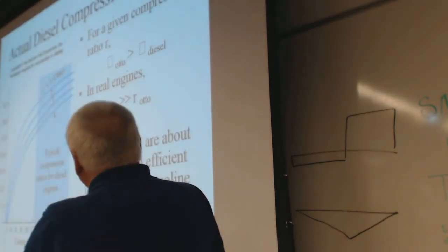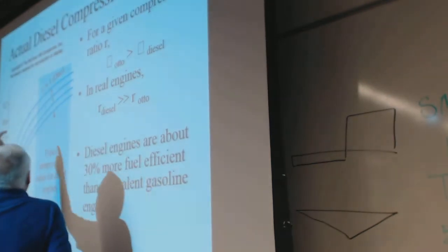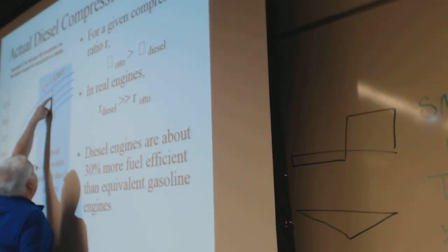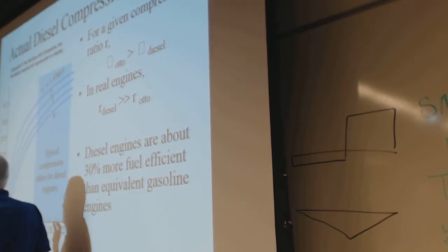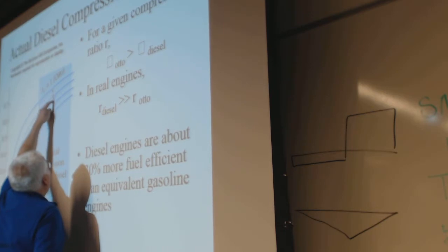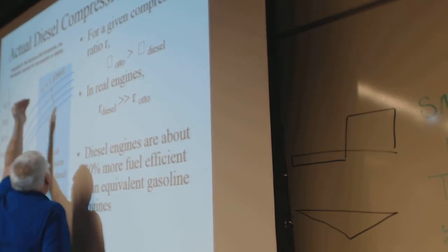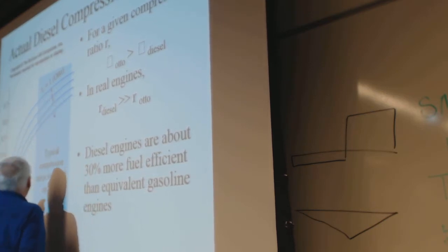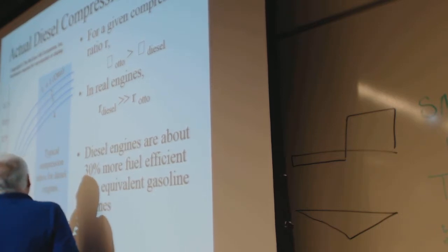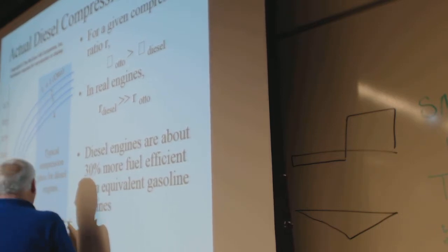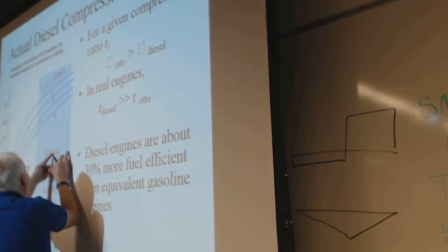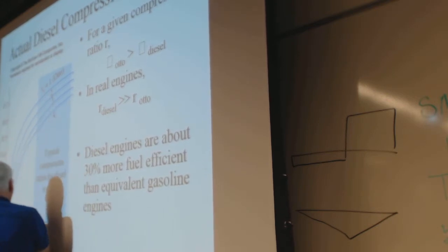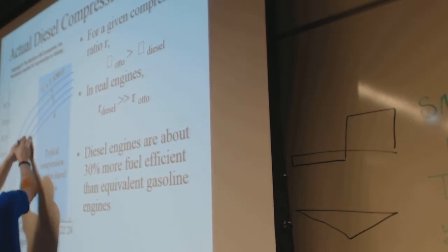As you put more fuel into it, the volume doubles before the fuel goes out. The volume triples before it goes out. The clearance volume doubles that volume. As you put more fuel in there, this curve starts dropping off, so you're actually getting less efficiency. But this is kind of the range at which diesels operate, and this is the range in which Otto cycles operate.